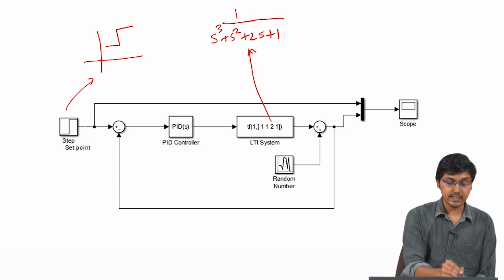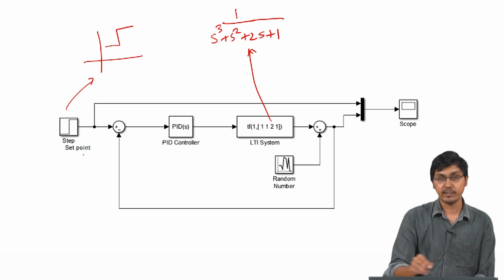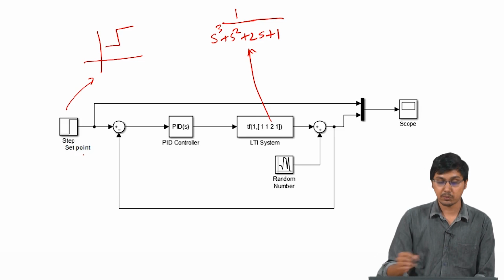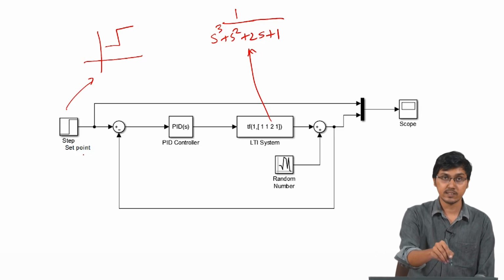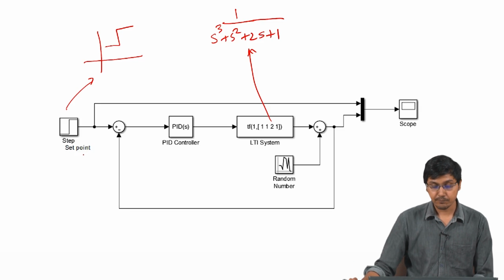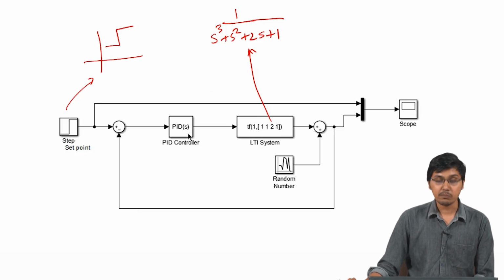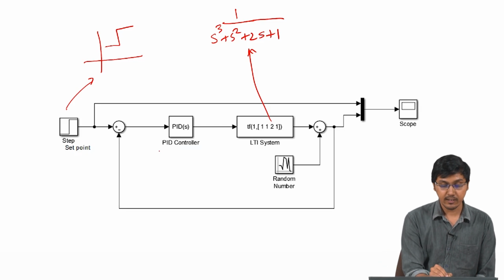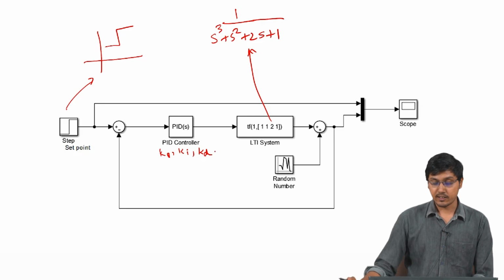We change the set point, and then we see how the output follows the set point; the input signal we give for the set point is nothing but a step input. And this is a PID controller block that is inbuilt inside MATLAB. It has Kp, Ki and Kd, and we are going to observe how the output changes.